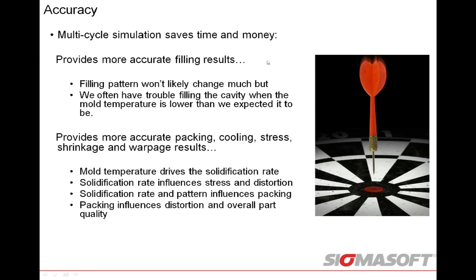First, it provides more accurate filling results. Now, the filling pattern probably isn't going to change that much depending on the multi-cycle, say if you run 5 cycles versus 10 cycles. But I have seen cases where you could have trouble filling a cavity because the simulation is saying the mold temperature is lower, so you're predicting a short shot situation. If you run just 1 cycle and you have a cold mold, then yes, it might predict that you're going to have a short shot.